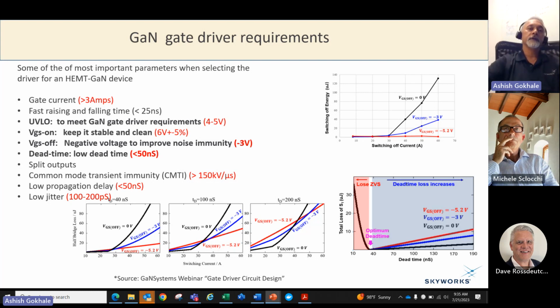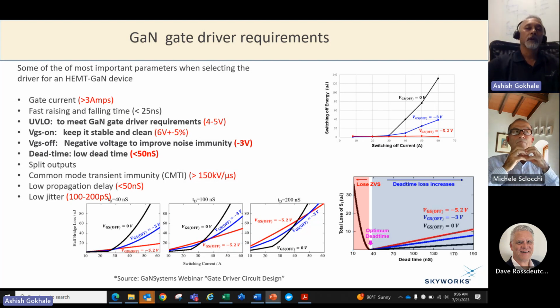A typical switch time could be, let's say, about 5 nanoseconds, and a typical DC link voltage, let's use 600 volts, is not uncommon. So you get a slew rate when you're switching 0 to 600 volts in about 5 nanoseconds. That's about 120 volts per nanosecond. If the driver cannot withstand that kind of high slew rate, then it can glitch.